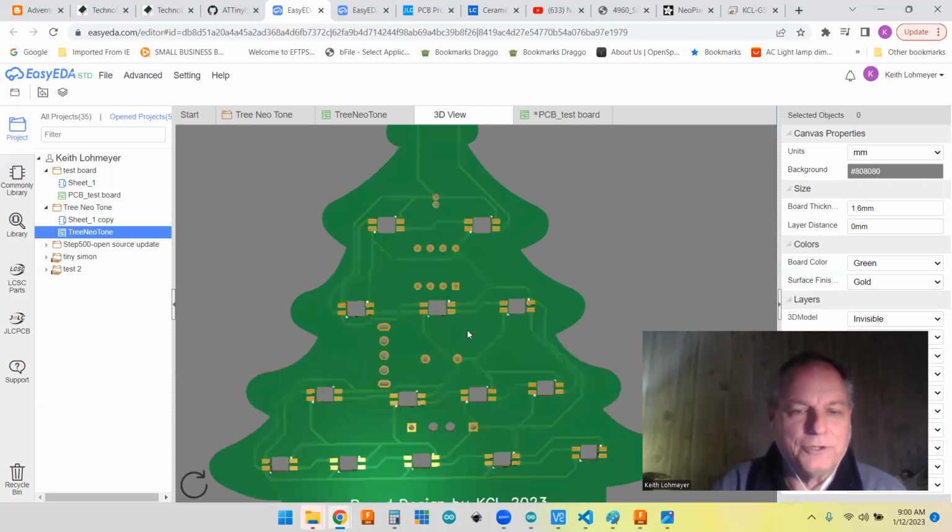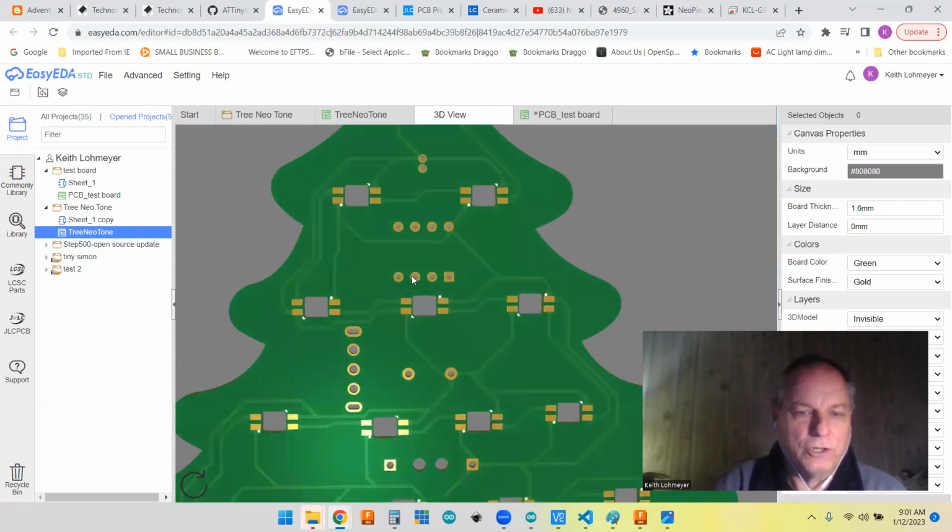I mean, you can see, these are the 0.1 inch or 2.5 millimeter apart on like the regular IC. So this is the distance between regular IC pins, and this is the distance between the pins on here. I think I'm going to get out a flux pen or something and try fluxing them before we flow the solder. That'll hopefully limit bridging and everything.